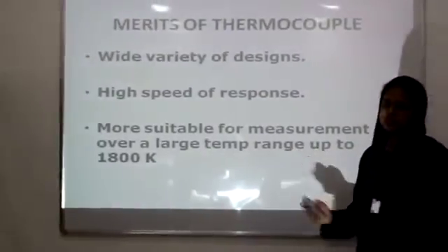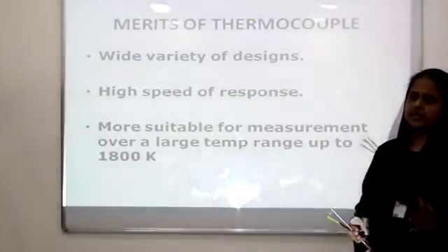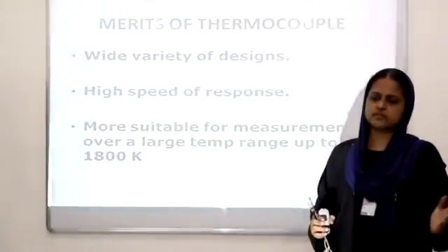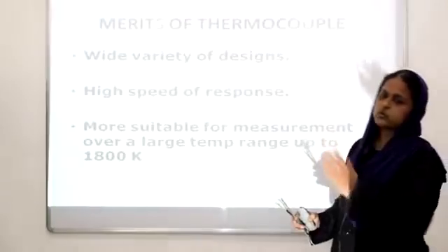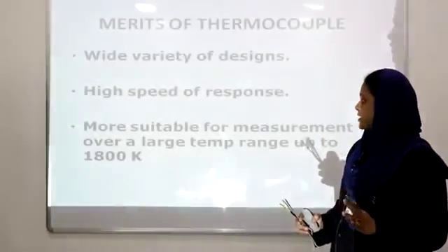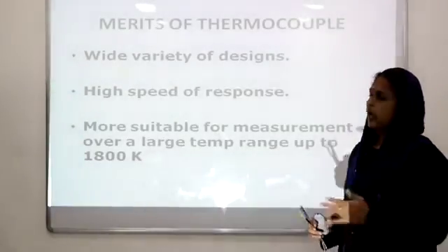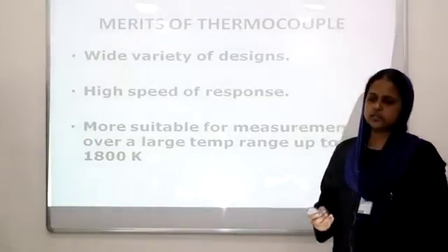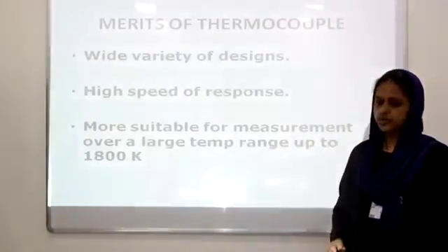So these are the merits of thermocouple. Why can I select a thermocouple? It has a wide variety of designs. I can start from minus 300 and extend up to some 3000 degrees Celsius. The speed of response is very high and it is more suitable for measurement over a large temperature range.